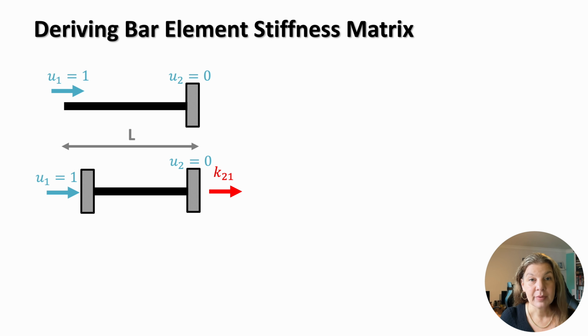As we discussed, the main idea of this method is to derive the load displacement relations between the displacements and forces at the end of a structural element. As we just saw, to do this, we impose a displacement at 1 degree of freedom while holding every other degree of freedom fixed. We then find the end actions that are required to maintain this state.